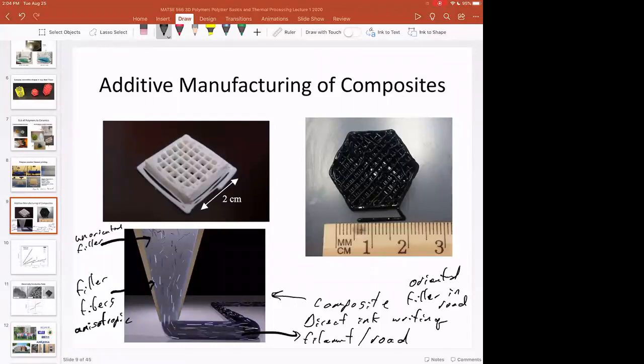That's because you have to squeeze the material through this orifice, and this orifice is going to be on the order of 300 microns or something like that. As you squeeze a fluid through that small opening, the fibers can't fit in sideways, and so they have to orient. Now you get really different material properties in the extruded road than you get from having some unoriented isotropic mixture.